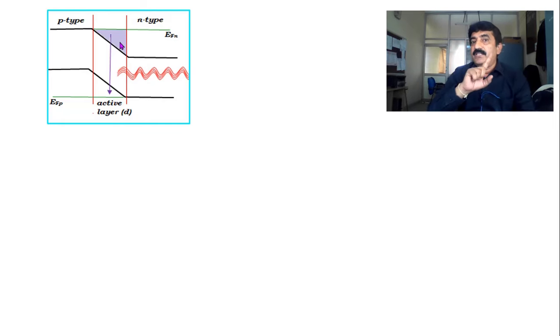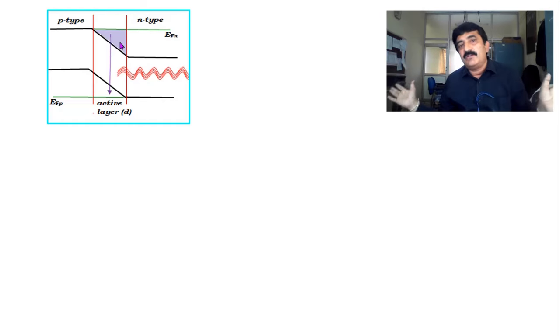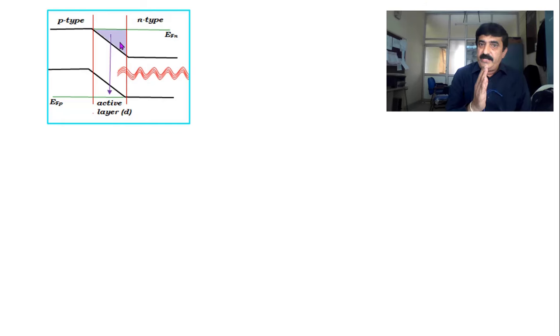But for me, it is not just ordinary light. I want more number of photons. All of them must be emitted simultaneously. For that purpose, I go for a heavily doped semiconductor. I increase the forward bias voltage. So finally what happens? The number keeps on increasing here. Population inversion takes place. And then stimulated emission. Immediately after population inversion, there will be stimulated emission. As a result, the laser pulse is emitted. This is the working.